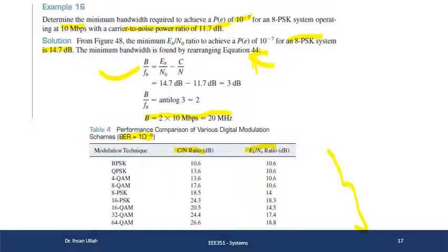So if you see, let's compare 64 QAM, in this you need Eb/N naught of 18.8 to achieve a bit error rate of 10 to power -6, whereas in the case of BPSK you just need 10.6 dBs, okay, Eb/N naught to achieve the same bit error rate, although you are sending more information but at the cost of power. Yeah, so there is nothing free, everything has a cost associated.